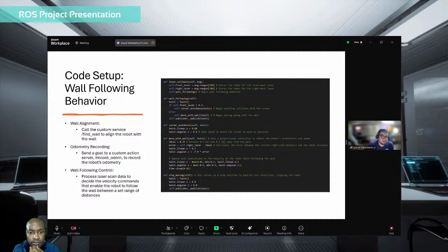The reason I chose a higher speed than recommended is, I believe the professor recommended from 0 to 0.49 radians per second. I tried doing that and sometimes it would turn left, other times it would just bump into the wall. So I chose a higher value just to make sure it actually turns left.